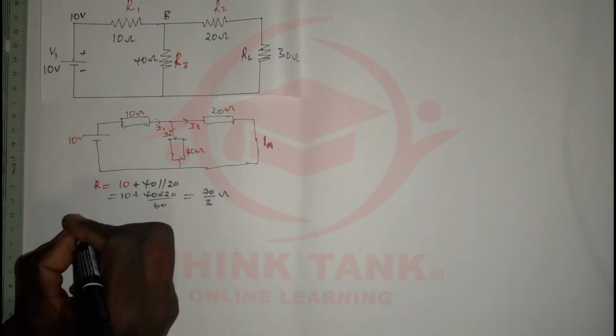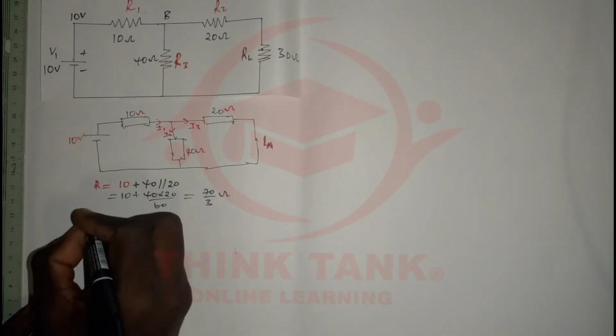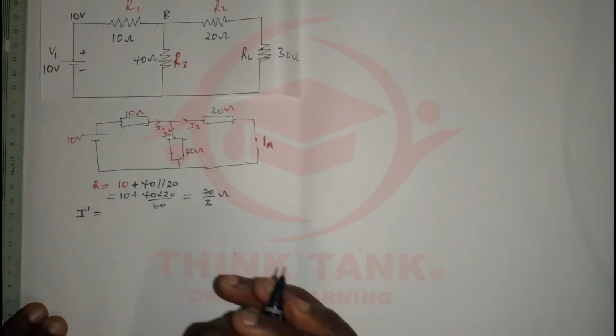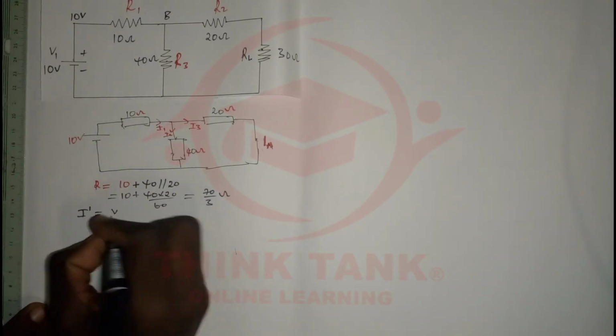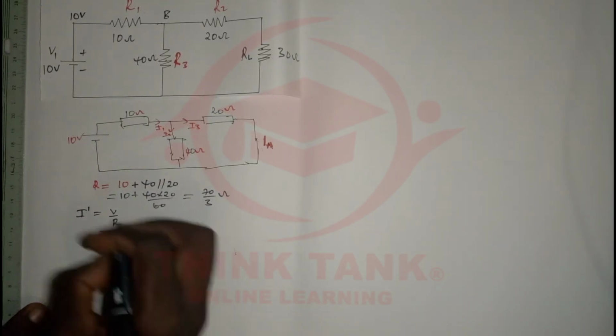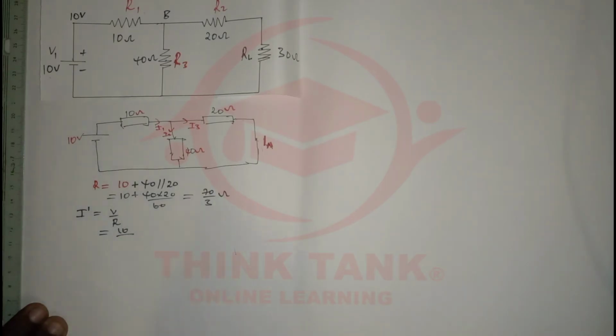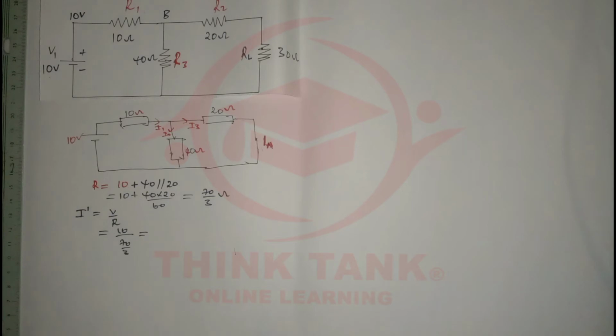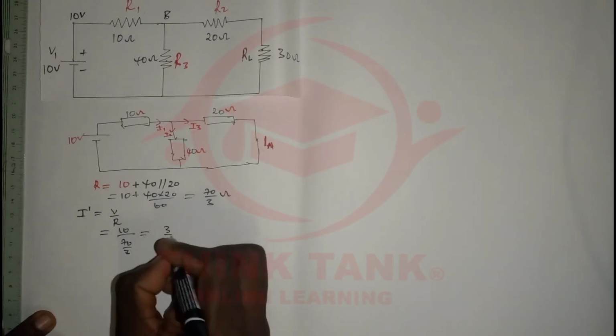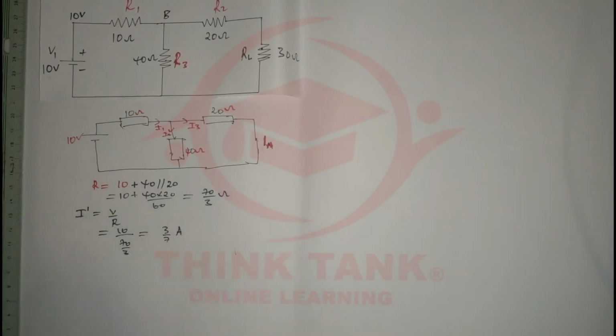Now that I have the resistance of the main branch, I'm going to find the current. Let me just call it I bar. We know that V equals IR, so if we make I the subject of the formula, it's going to be V over R. Voltage is 10, and the resistance is 70 over 3. So that is going to give us 3 over 7 amps. So 3 over 7 amps.